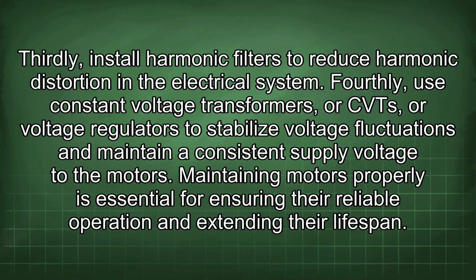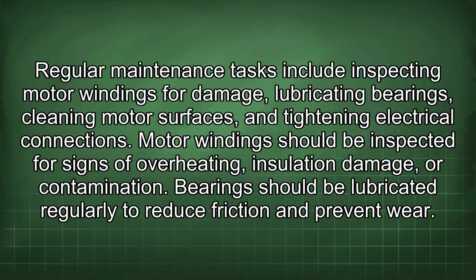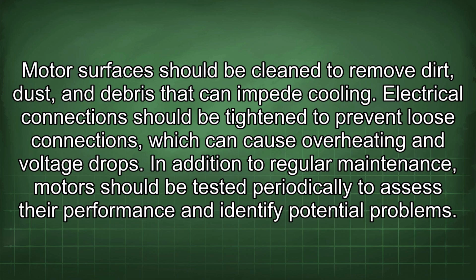Maintaining motors properly is essential for ensuring their reliable operation and extending their lifespan. Regular maintenance tasks include inspecting motor windings for damage, lubricating bearings, cleaning motor surfaces, and tightening electrical connections. Motor windings should be inspected for signs of overheating, insulation damage, or contamination. Bearings should be lubricated regularly to reduce friction and prevent wear. Motor surfaces should be cleaned to remove dirt, dust, and debris that can impede cooling. Electrical connections should be tightened to prevent loose connections, which can cause overheating and voltage drops.